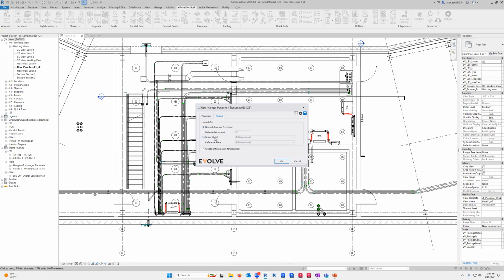However, for a lot of people, you're working with linked models. So you'll have a structural model and an architectural model in your links. Both of those will have floors. However, they're only going to build those floors according to one model, and that's the structural model. So sometimes the architectural model has the floors lower. They might do 12-inch floors as that's what they model, but the actual floors are going to be 6 inches or 3 inches, and it might be a pan deck or something like that. So commonly, you'll want to come in here and select linked model and choose your structural model.